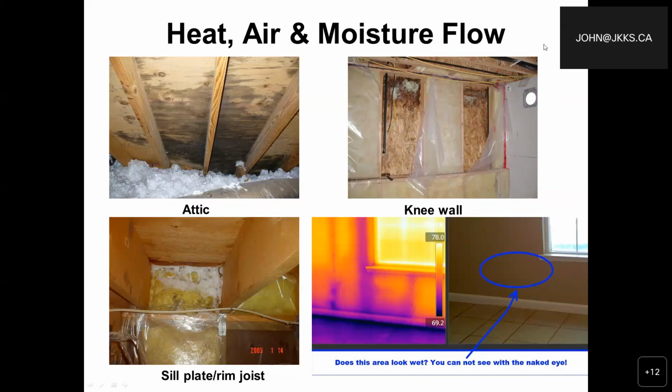My understanding is, if you're building a new home and you put a radon gas mitigation strategy in up front, it's only a few hundred dollars. It's piping. You put in special pipes that you seal. But if you build a home that has radon gas, then it could cost you thousands of dollars. You have to drill into the foundation and relieve the pressure. Then you have to put in these vacuums to suck it out, and then push it out.